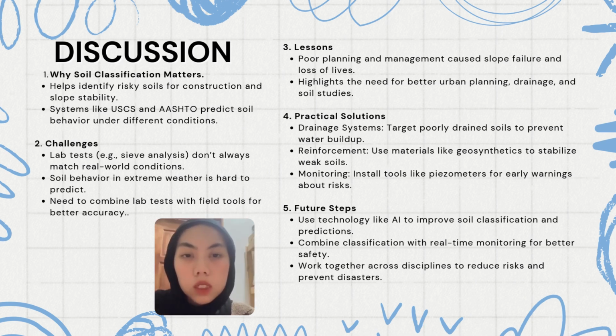Next is challenges. There are challenges with soil classification. Lab tests like sieve analysis don't always reflect real-world conditions, especially during extreme weather. That's why we need to combine lab test results with tools like piezometers for more accurate predictions.